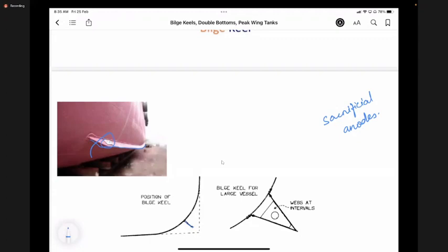So if we have the sacrificial anodes, there are some calculations required for sacrificial anodes, and when in salt water, these anodes get eaten up by salt water and the nearby surroundings. For that reason, we put this. And many a times you will see in the ship near the aft end, near the forward end, mostly towards the aft end, we put these sacrificial anodes to stand by.